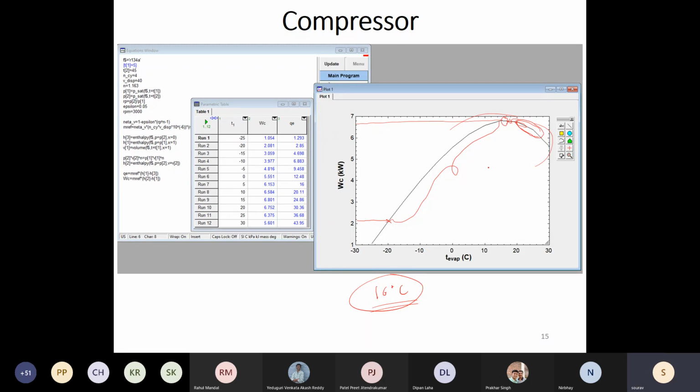Please remember this is different from the initial startup torque or startup current demanded by an induction motor. So this is purely from the compressor side. We are not discussing the motor. In your induction motor, just during the startup, a single phase motor will have a starting coil, and that will demand more current, and hence on the grid you will have a lot more demand.